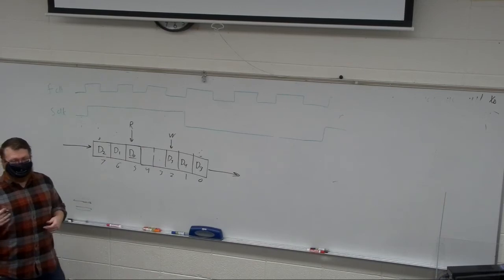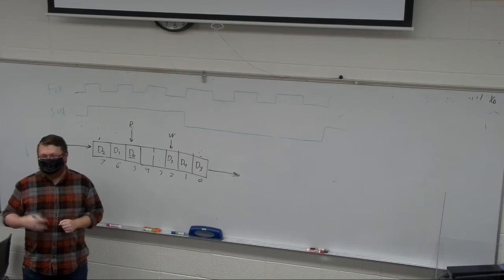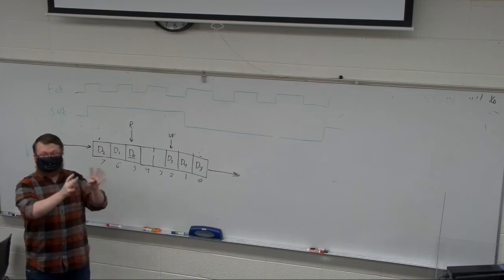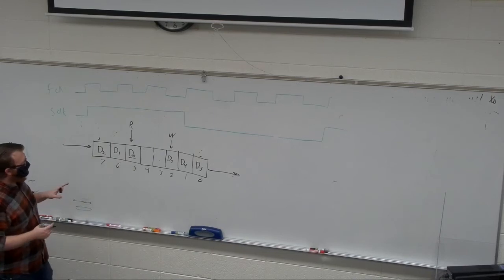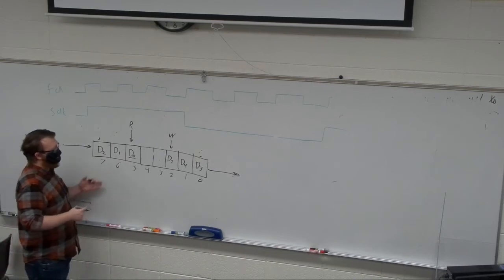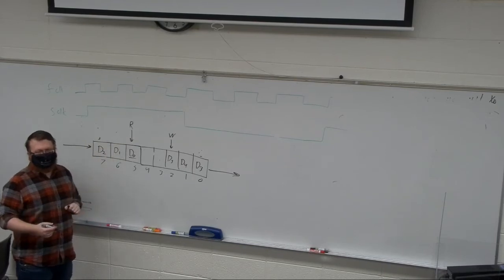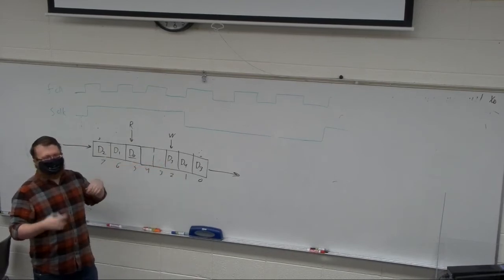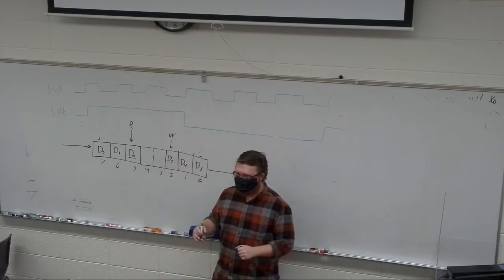Like we're using a UART and we're transmitting data out, but say we're sending data out from 6 different ADCs. And maybe generally these read out slow enough that the UART can push it out fine, but every once in a while one of them fills up with a lot of data and we're like, hey, this one needs to go now. Empty flags are the same kind of thing, which is to say that my read and write are almost at that same spot, we're almost out of data. And then it can start saying, okay, maybe I can prepare data to parallel load it, right? So almost empty, almost full, these are useful flags that you'll see on most good FIFOs.